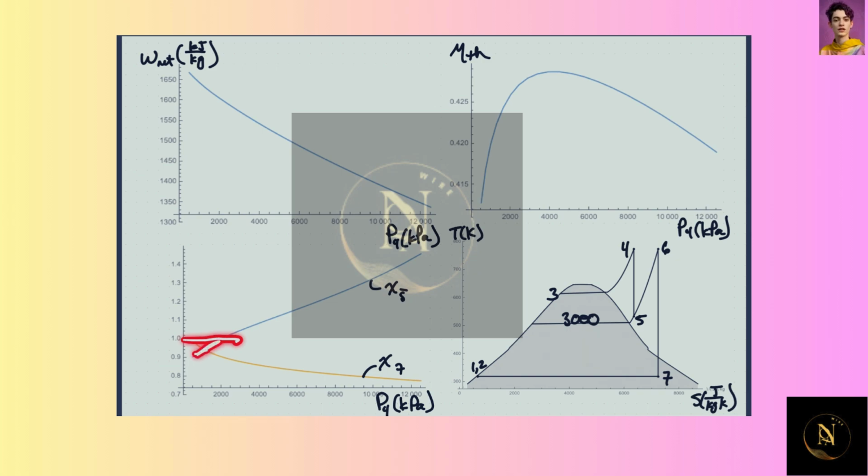So we're two-phase in both cases for these lower pressures out here, which we might expect, right? Because this is going to be the same here. So as we drop this down, we're going to wind up going into the two-phase. Here I took 3,000 as the example here. So we're slightly above 1. So we're slightly supercritical.